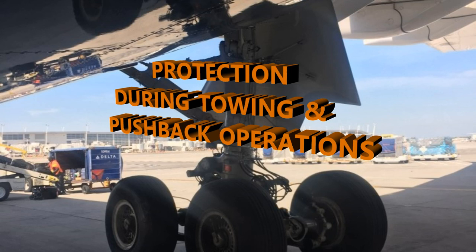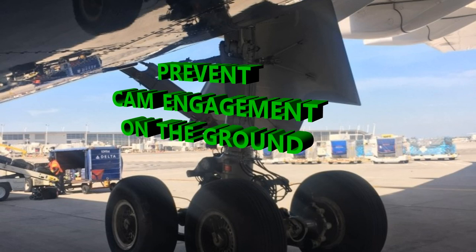What I'm referring to in particular is the centering. Typically when we have nose landing gear, the shock absorber has cams that are used to center the nose wheels during the sequences for extension and retraction. And when the shock absorber extends, that's when the cam on the sliding tube, which is the inner piston, engages into the cam on the main fitting. That way it causes that alignment. You don't want to have that alignment on the ground.